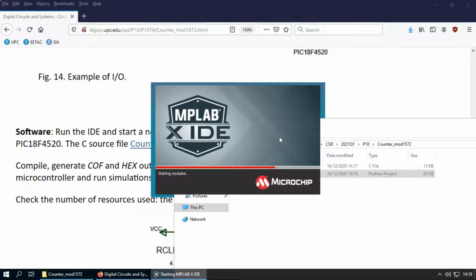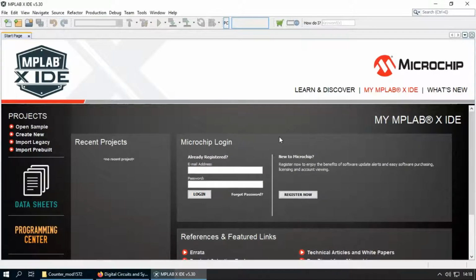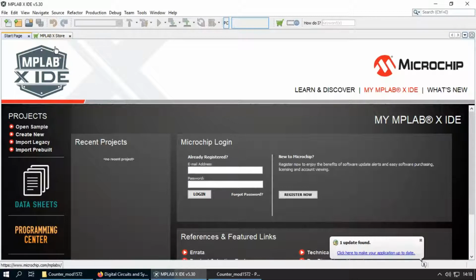A simple up counter of a given number of states. But if you like to modify it so that it's counting up and down, after you've got your sketches and you know what to do in the software, you make the modifications, you add the necessary variables or whatever it is, and in the end you try with the hardware at the same time, because there is a modification here as well in the hardware. You have to add the up-down pin and read it, etc. Right? So you can do that a lot better if everything is working at the same time, the hardware and the software.